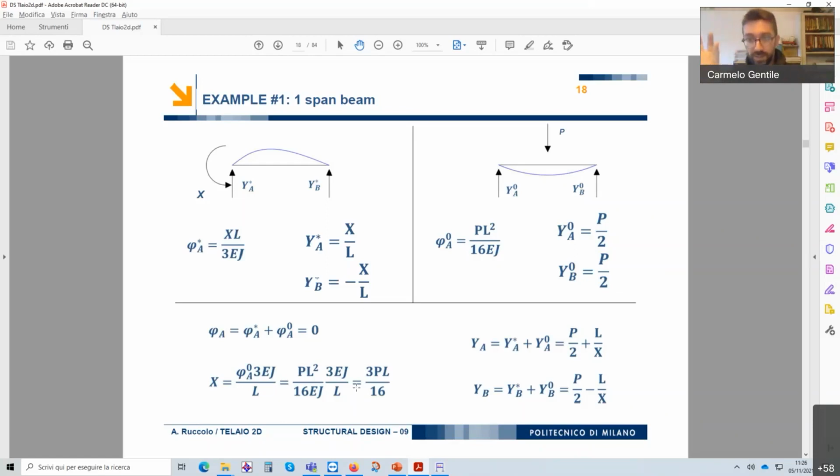So for statically redundant structures, if the structures are homogeneous, the distribution of force does not depend on the distribution of stiffness. So material and cross-section. If the redundant structures are inhomogeneous, are heterogeneous, then the distribution of forces will depend on the distribution of stiffness. Okay? We can have other examples later on, but it is better to see them with an example.